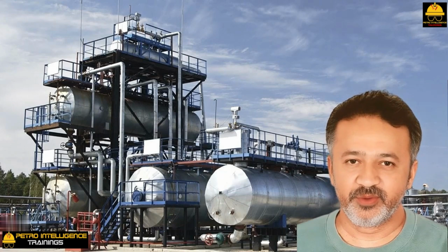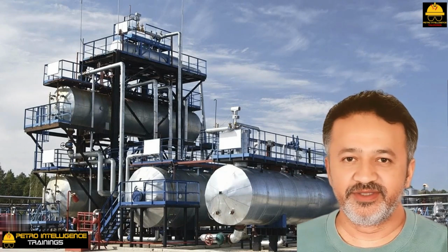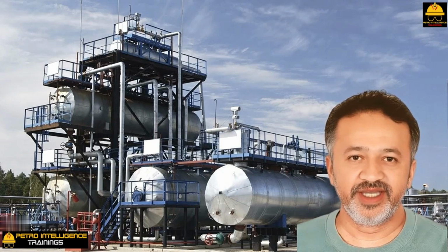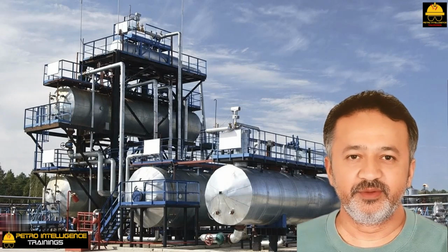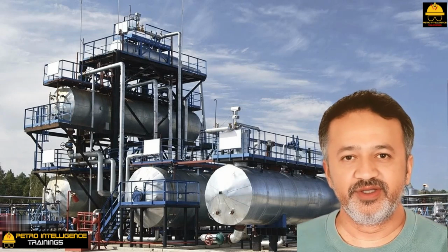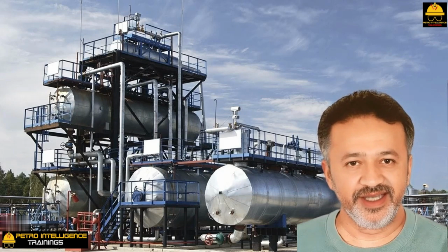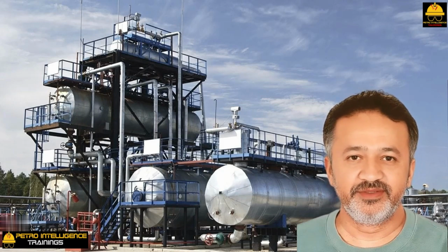Demineralized water is preferable to hot lime softened water as boiler feedwater for several reasons. For one thing, steam produced from hot lime softened water will have some amount of silicates. These silicates tend to deposit on the rotor blades of turbines, which use the motive steam as a source of energy. The silicate fouling of the turbine blades reduces the turbine's efficiency.